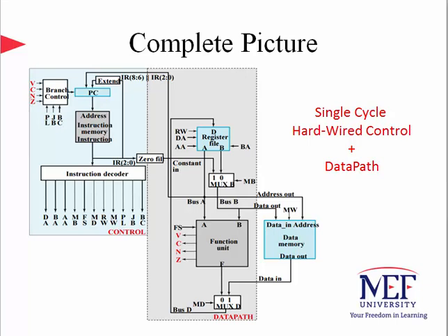If we combine the single-cycle computer data path with the hardwired control logic, we will finally have this circuit schematic. Don't worry about what hardwired control means at this stage, as we will have more time to discuss two major control methodologies for computers in our next session. But here you can note that instructions read from memory are decoded by an instruction decoder. In fact, the instruction decoder is the main logic of the control unit. If it is implemented using simple combinational circuits, it's called hardwired.